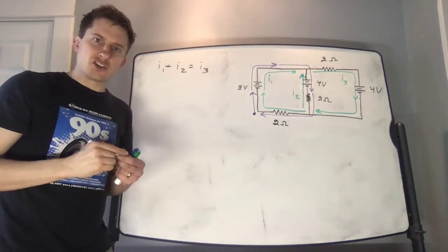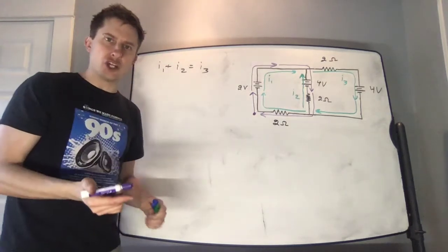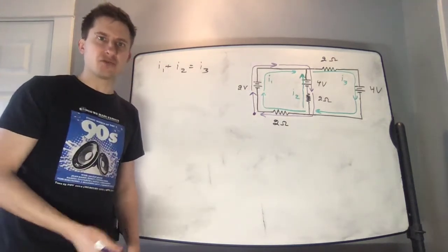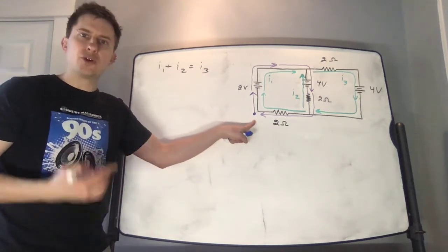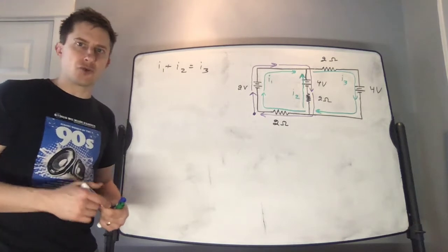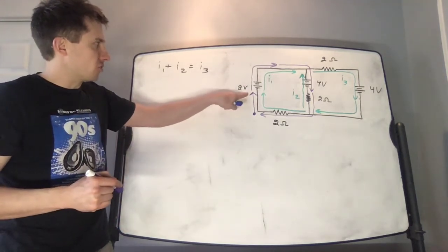As we cross the circuit elements when we are traveling around this loop, we will record the change in voltage using the rules from the previous video. And when we return to our starting point, we will set the total change in voltage around this loop to be 0. I begin by walking upwards through my circuit.